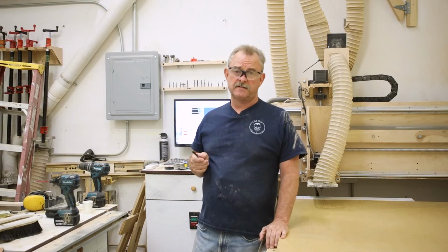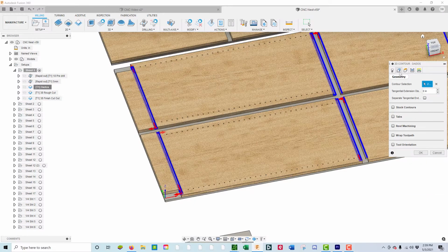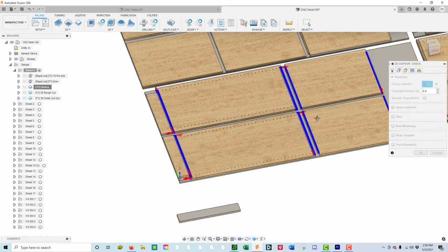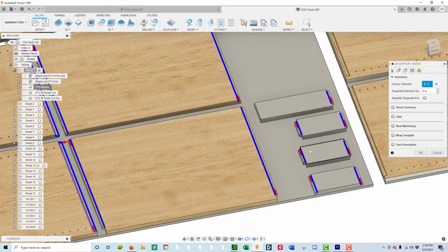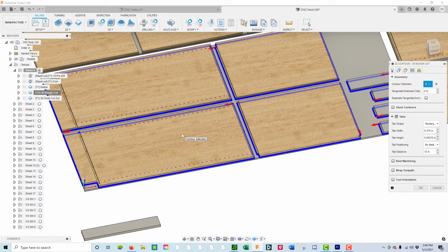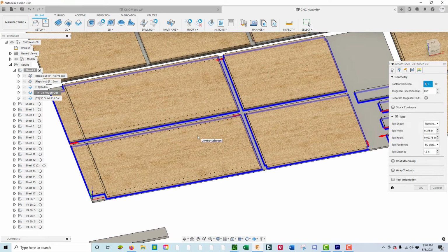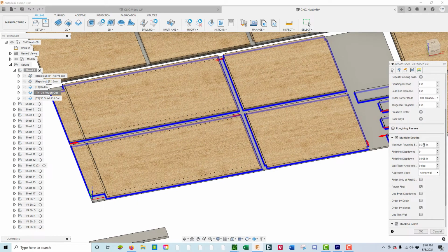And probably the nicest thing about CNC milling is using this. A 3/8 compression end mill. First I lay out all my dados. That's just going to take a 1/4 inch pass on all these lines. The second operation with a 3/8 is going to be cutting the rough out borders. I have to do this in 2 passes because my CNC or my spindle is not strong enough.